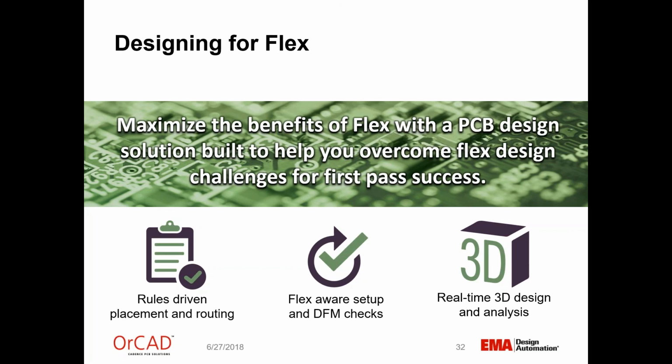When viewing the 3D model, how do you rotate the design, and is there a function key needed in conjunction with the mouse cursor? Yes. What you're going to do is hold down the shift key and use your middle mouse. Then you can rotate it, move it any way you want to. Rolling the middle mouse roller zooms in or out. You can hold it down and move the picture around. So it's pretty much all controlled with the middle mouse key, but rotating it requires a shift.